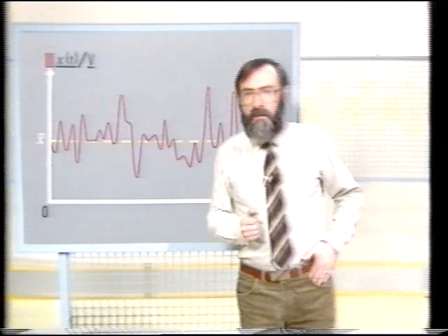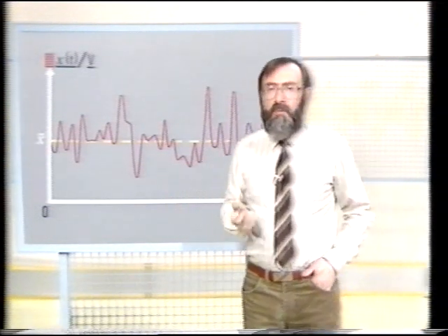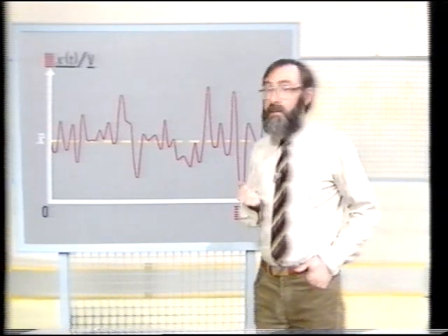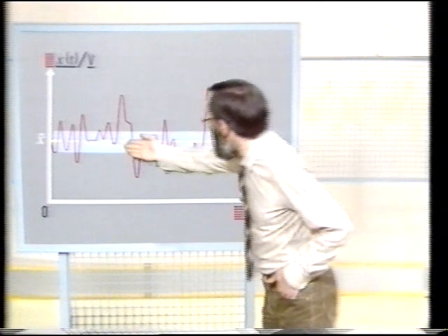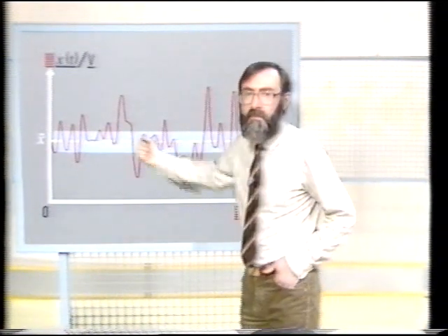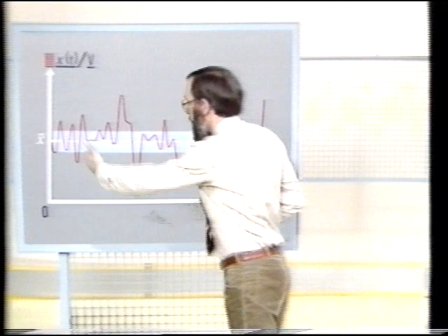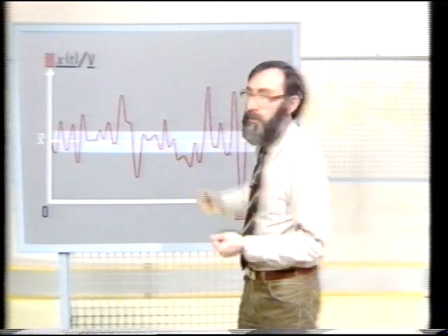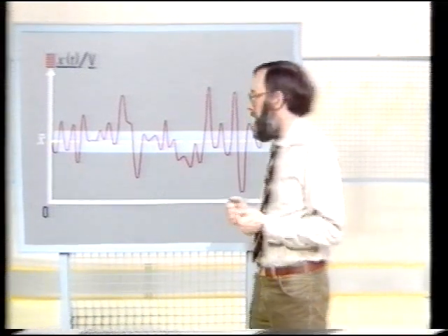But the statistical approach to modeling goes on to ask what the probability might be of finding future values of the signal within a range of voltages, like this one here, for example. Now, past behavior tells us that the signal has spent a relatively high proportion of its time within this voltage range.